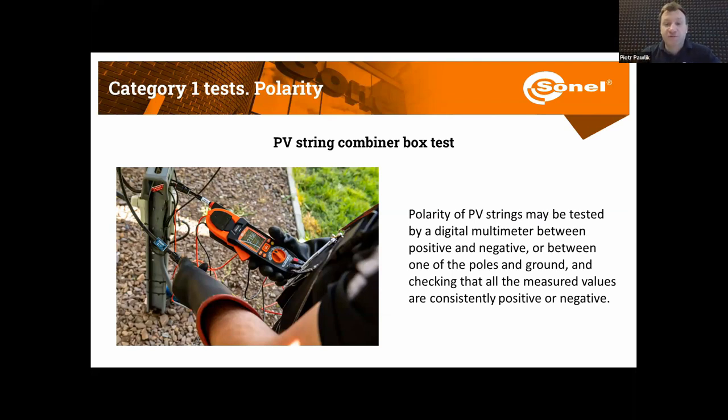So the recommendations from the standard go this way. We need to check the voltage on the first string, and this is going to be our reference for later. Then insert all negative connectors, since the strings share a common negative busbar. We do not insert any positive connectors.